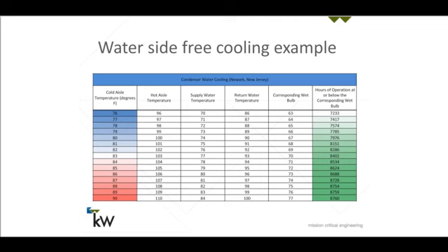We used to think of waterside economizers where you're primarily running chillers and you're using the cooling towers, or you're providing free cooling for fewer hours than the mechanical cooling. Now it's the other way around by a significant margin.